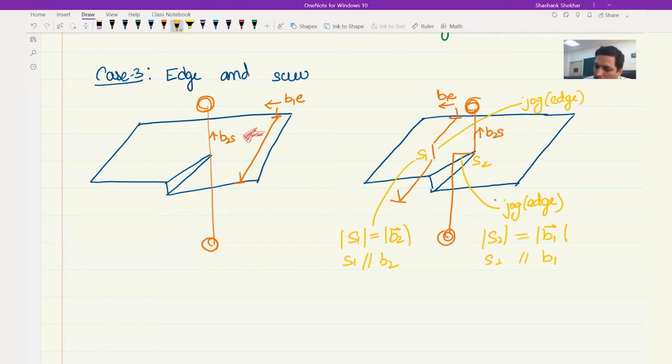is that this particular dislocation that we see over here, this step, wants to move in this glide plane, and this is the glide plane. So it can move along with the rest of the dislocation, and hence it can aid in glide. However, for this one, what we see is that this is the dislocation, this is the step, and this was the original plane on which it wanted to move. But for this one, let me draw it over here.